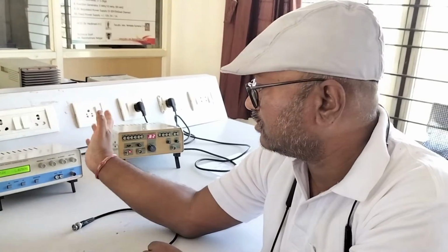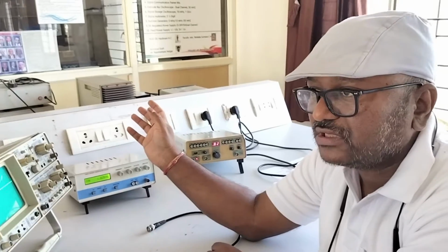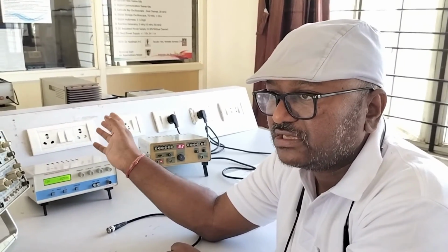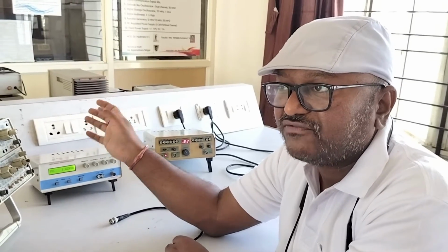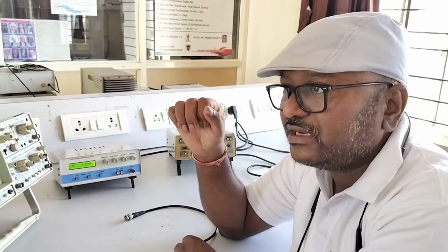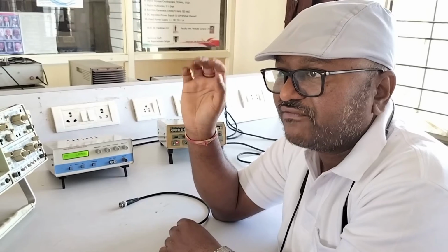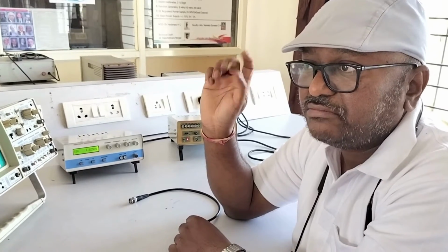So in this case, there is confusion about how to adjust the voltages with the function generator. Every student has this doubt, because the range given is 0 to 20 volts peak to peak, but there are two attenuation buttons, 20 dB and 40 dB. So when to use 20 dB and when to use 40 dB? What is the position of the attenuation levels, how to select the frequency, how to adjust the amplitude, these are the things one must know.